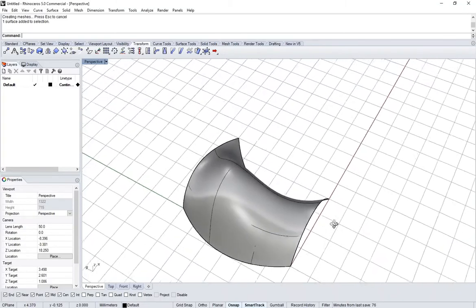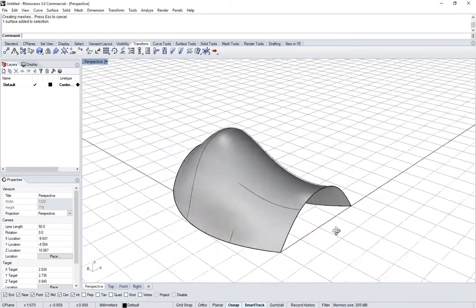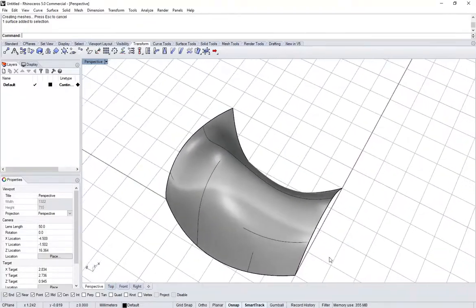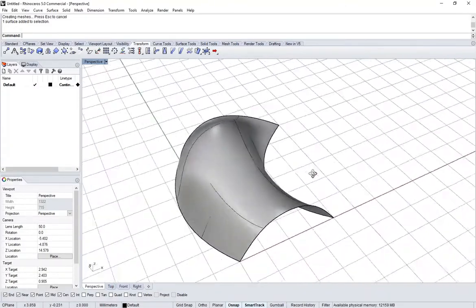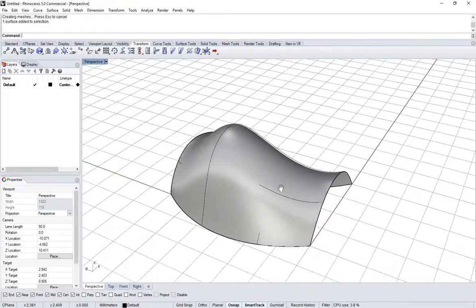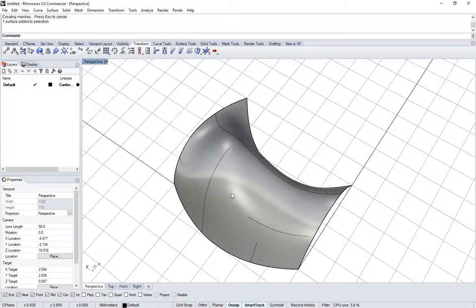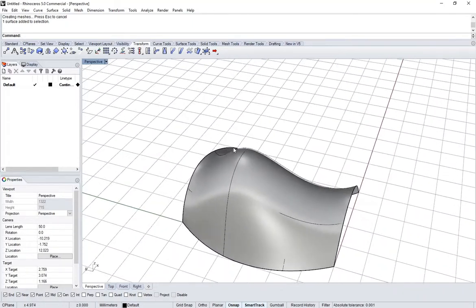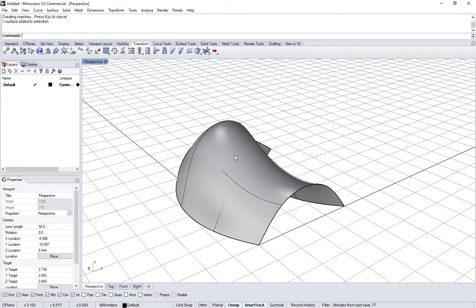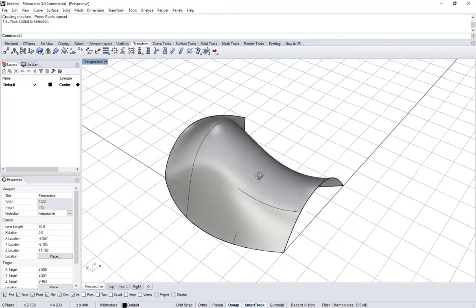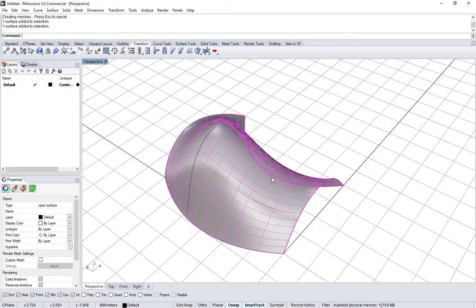So, like I mentioned before, all surfaces in Rhino are topologically basically a rectangle that can be deformed as much as you want. So it gives you a lot of control over the curvature of the surface, but not necessarily a lot of control over the boundary or the interior topology. So often when we're working with surfaces, we not only define the shape of the surface, but we also define its boundaries through intersections and splits.